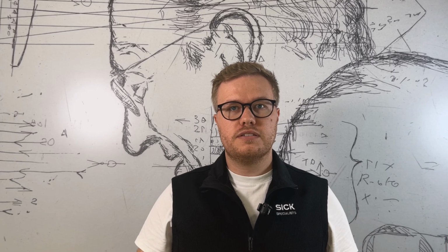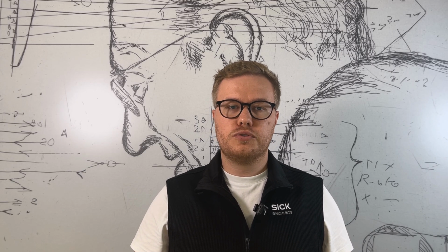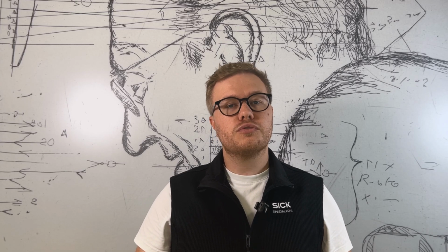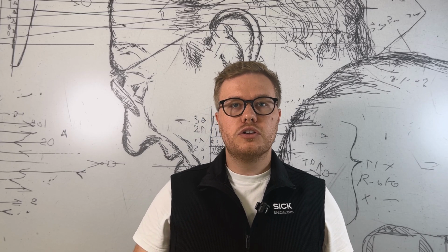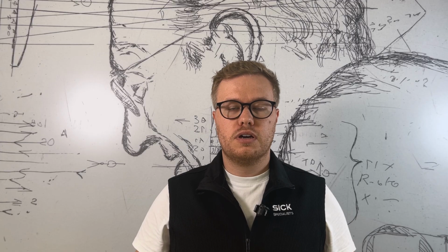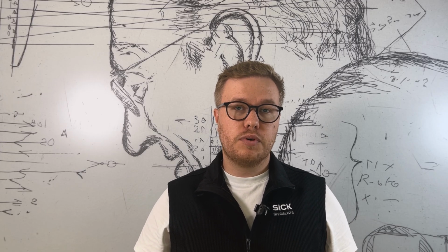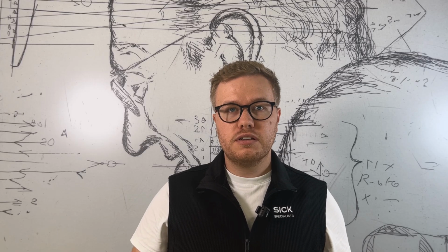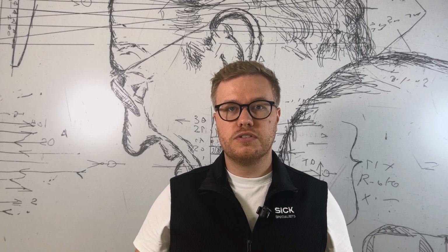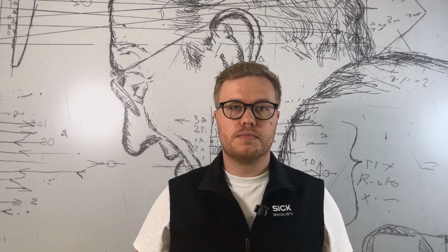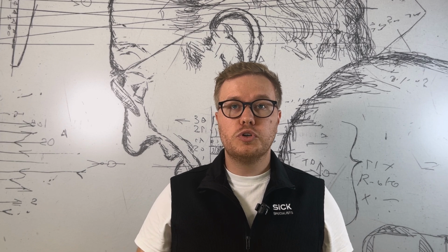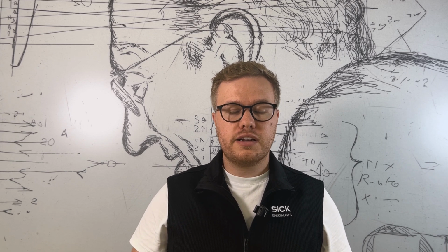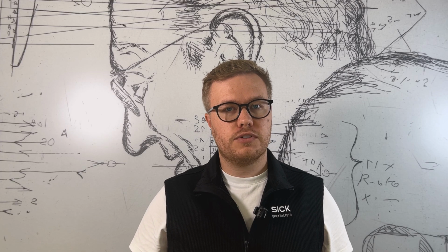The secret of the ASIC is the digitization of the photocurrents directly at the pixels. This reduces noise and increases sensitivity. This alone brings an increase of performance. However, we achieve the biggest lift when we process the digital data. We can play around with this data and create new features and customer benefits through digital signal processing. By the way, most optical experts are taking advantage of this opportunity. But what exactly happens now with the ApplicationSelect function?